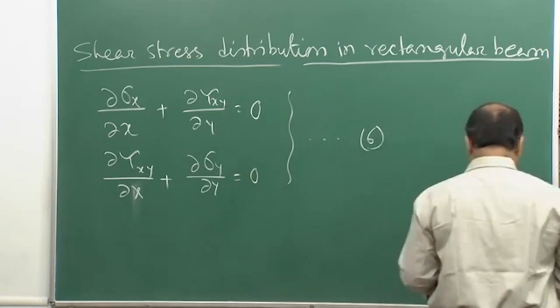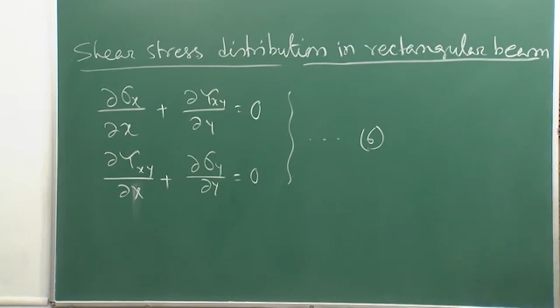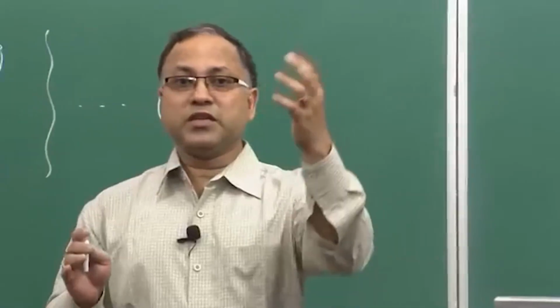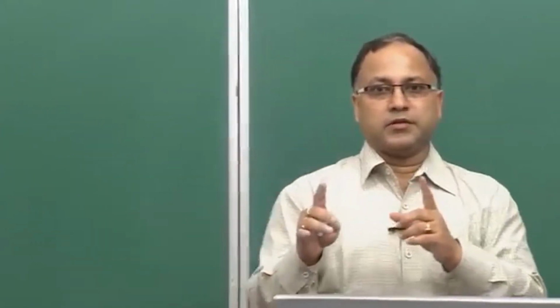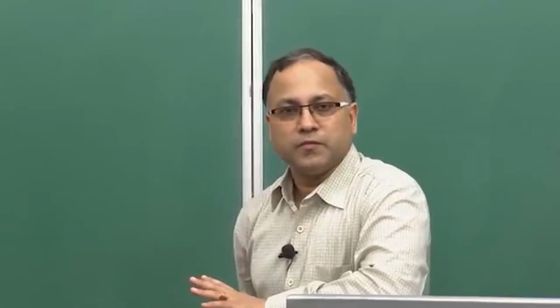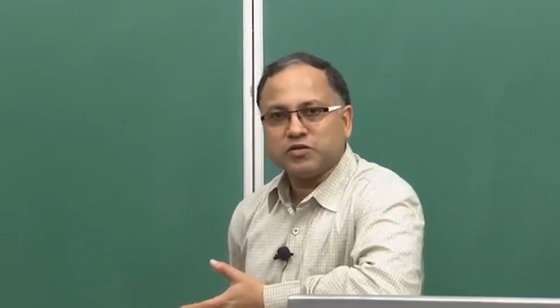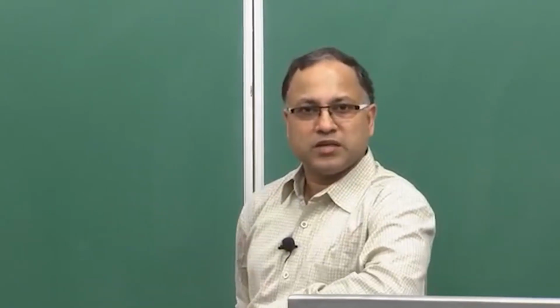Now, if the shear force does not vary with x, as we have discussed in the last lecture, because there is no transverse load, the shear force is not varying with x, only the bending moment is varying. Since bending moment is varying, therefore shear force exists, but it does not vary with x. Then the shear stress will also be independent of x, agreed or not. If there is no variation of the shear force, then how will the shear stress vary with x. So, shear stress will always be independent with respect to x.